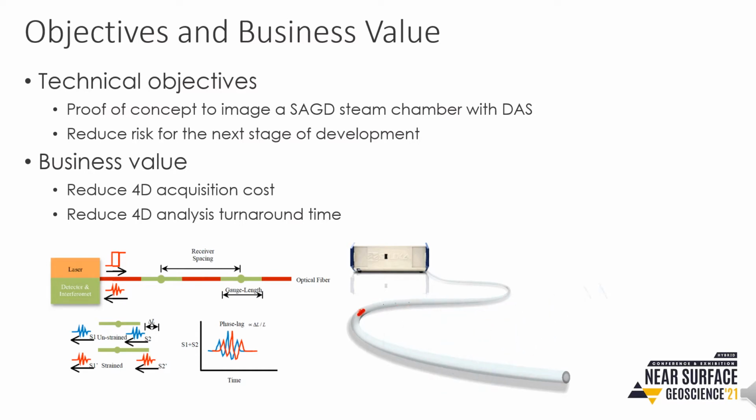Surface seismic data were acquired over the years in the field to monitor the steam chamber growth in order to reduce the risk of the next stage of development. Fiber optic sensor cables were deployed to provide a continuous well temperature profile for steam management and production optimization.